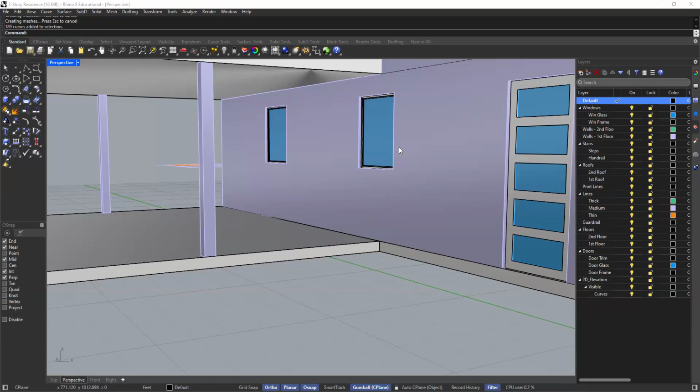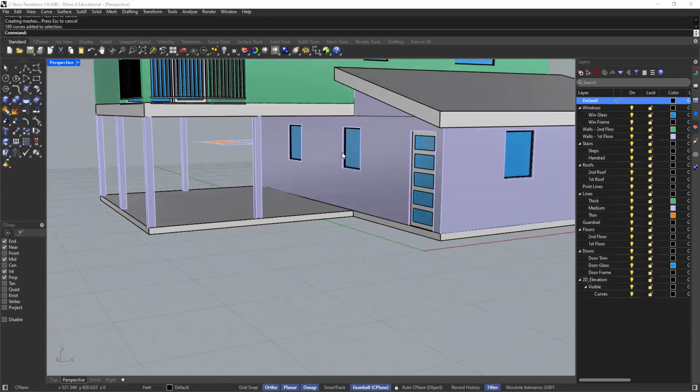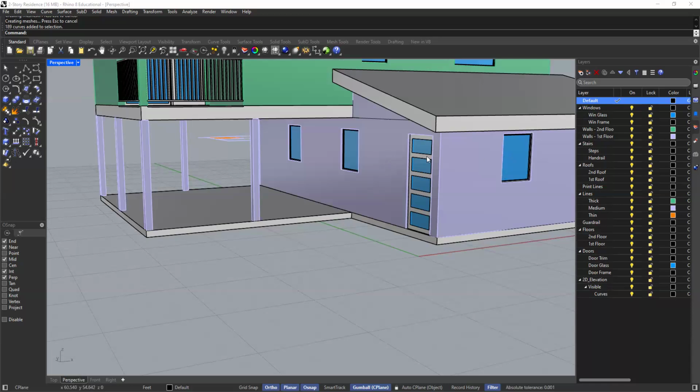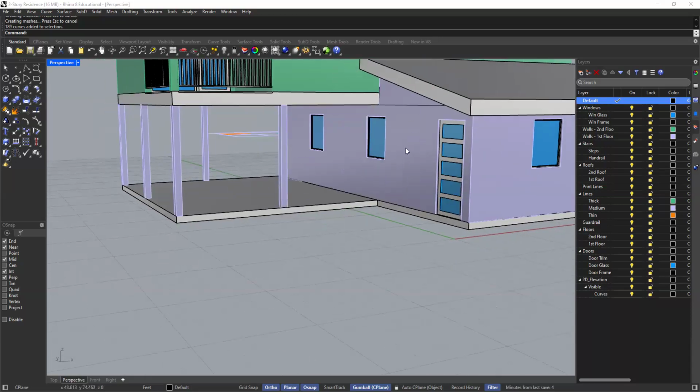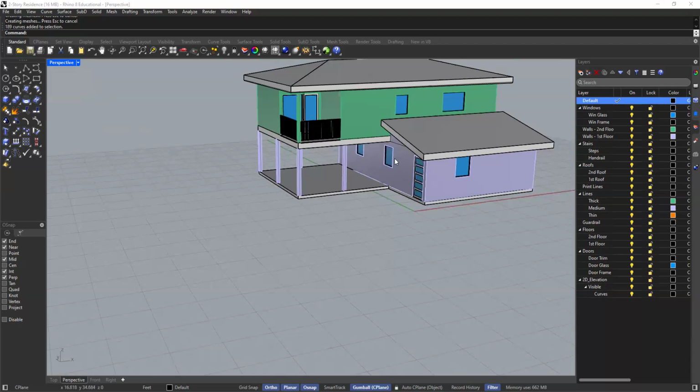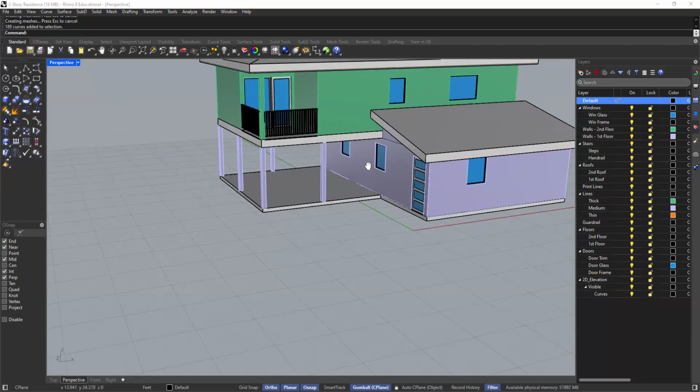But if a floor plan does specify a height, let's say you wanted a floor plan shown at 5 feet or at 3 feet or at 6 feet, whatever height you want, then you would just specify that in the drawings in the bottom right corner, where you would name it, let's say, first floor plan at 5 feet, right? But most floor plans are taken 4 feet above the finished floor. Okay. So we're going to go ahead and get into creating this floor plan.